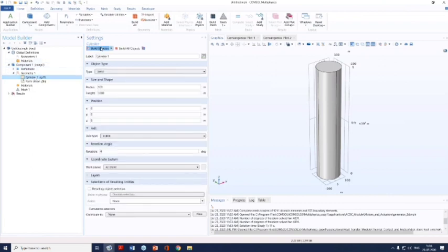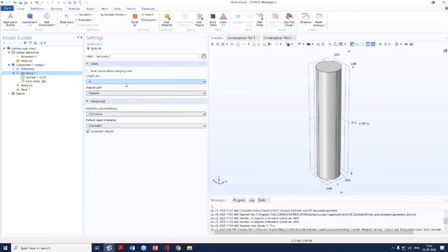And if I go back to this cylinder, you will see that now I have arrived at 1000 meters, without explicitly changing the number over here. Rather, I just played with the scale values while changing the units. Again, in this case, it's just one object, which is why you may think that directly changing this value manually might be easier. But if you have lots of steps under your geometry sequence, then using this scale values while changing the units would definitely be helpful.